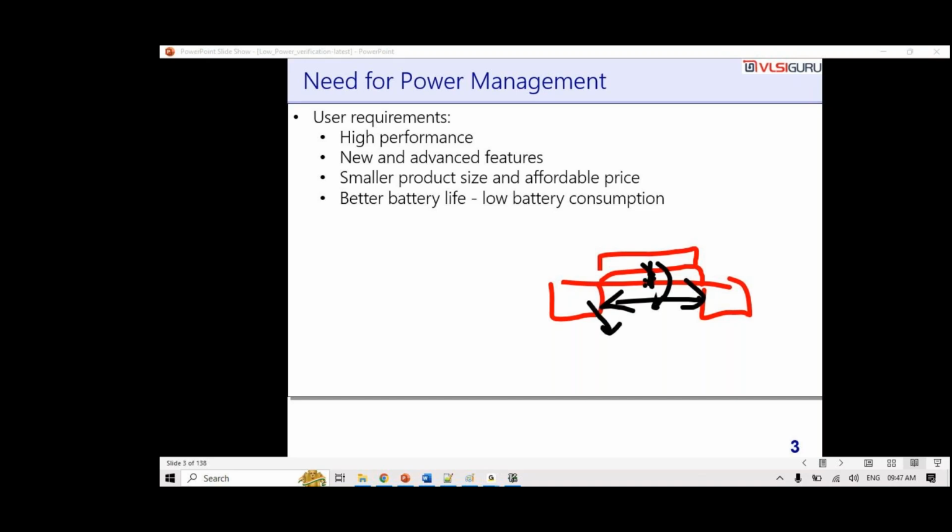So they become more and more prominent. There will be some unwanted structures that get created between drain and substrate, source and substrate. There is an unwanted flow of current from gate to the substrate, which all leads to the leakage current, which is unwanted. Those are all problems that come because, as you reduce the product size, the leakage current increases. Now it has become so significant that it is on par with the dynamic power consumption. It was not a problem in higher technology nodes. Let's say we are talking about 90 nanometer, that wasn't a problem. Above 180 nanometer, or in that range, it wasn't a problem. But now, when we are moving to lower technology nodes, it is becoming a significant problem.